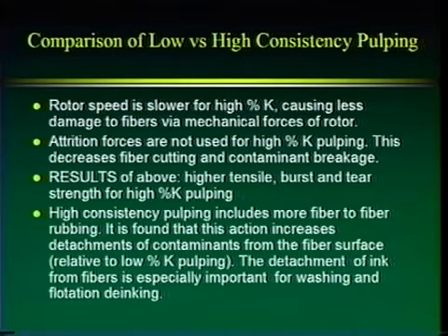Okay, now the other thing that high consistency pulping does is, because there's more fiber to fiber rubbing, that action detaches contaminants very well. So the detachment of ink from fibers is especially important when we're going to do de-inking. So high consistency pulping is often used prior to de-inking.